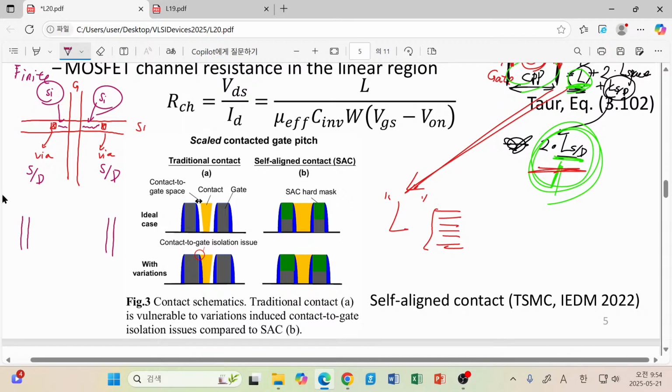Let's say that this is metal, and now here we have highly doped source and drain regions. So this is, for example, N plus and N plus in the case of an NMOSFET, and here we have now the gate. The conductivity shown here is controlled by our gate-source voltage. Yes, we have studied that up to now.